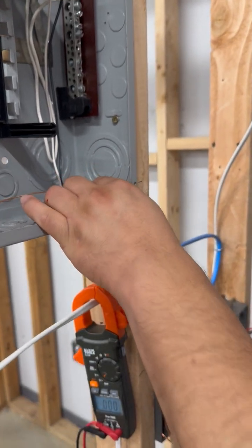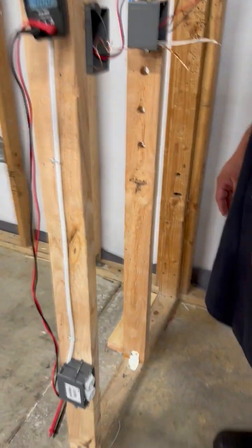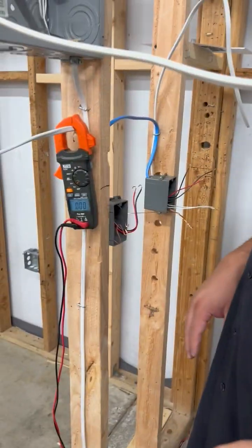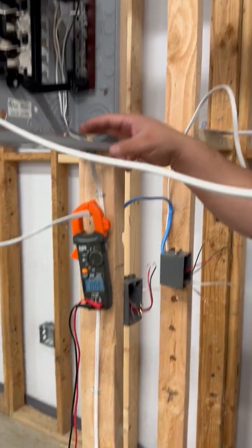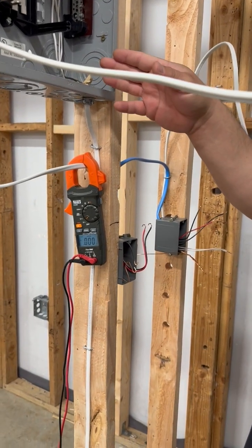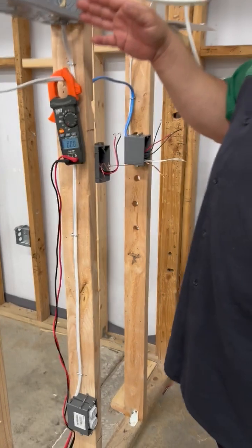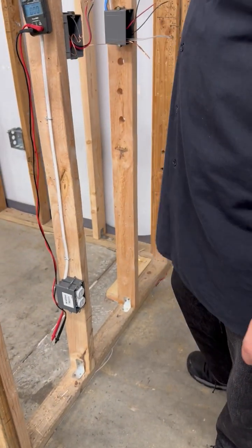And that's where we're going to have that short circuit, that ground fault. So look for those small defects before you energize, because there's nothing more embarrassing as an instructor than not catching the ground fault or short circuit that's obviously visible by a bare conductor being cut.